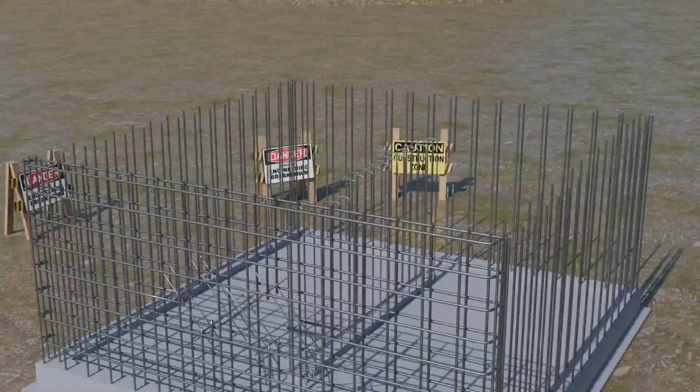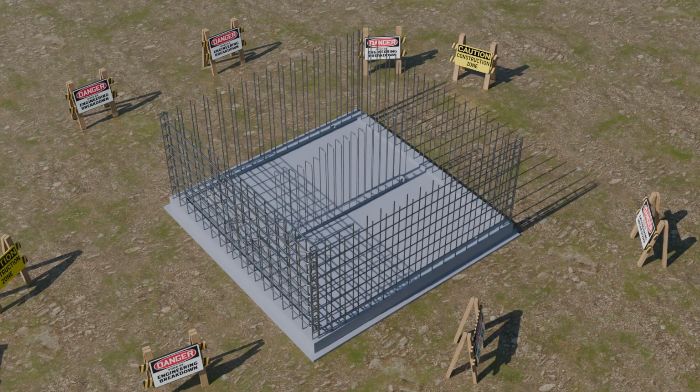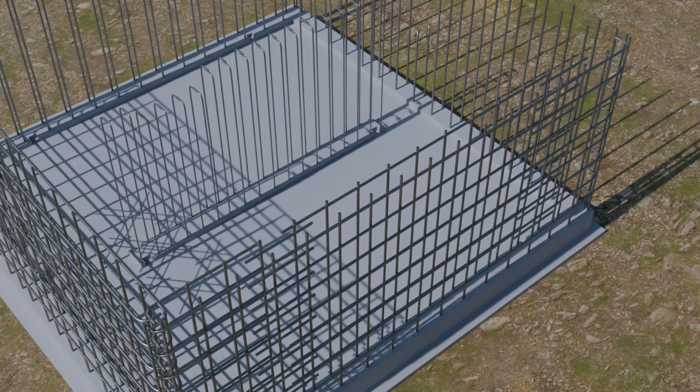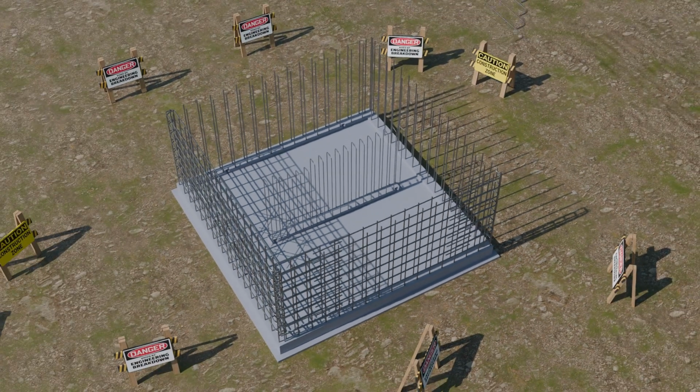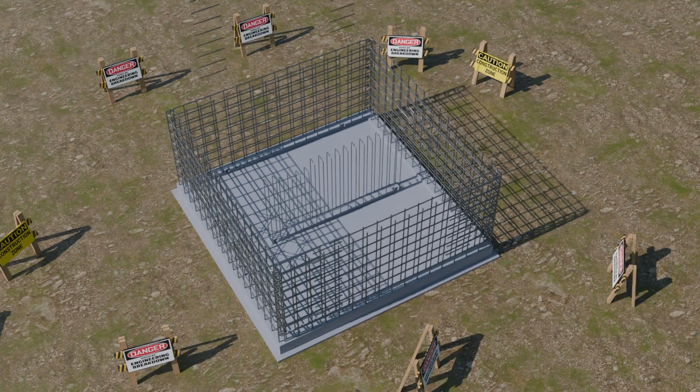For the side walls, the horizontal reinforcement is here cut and arranged in segments to match the wall geometry, including any recesses or indentations needed for installing mechanical gate slots. This process is repeated for each wall to complete the overall reinforcement layout.